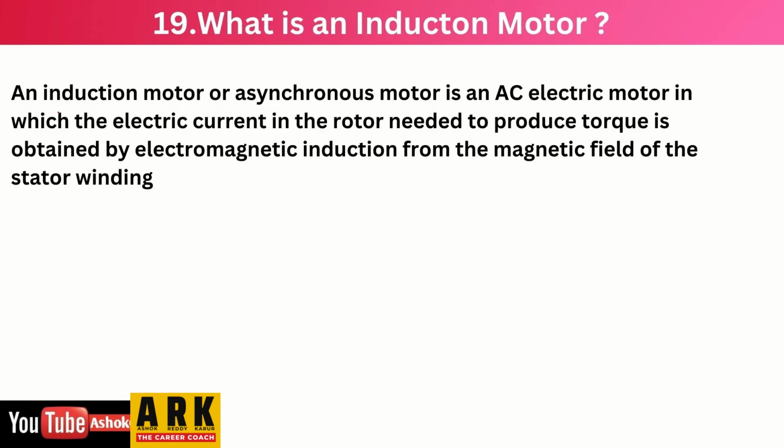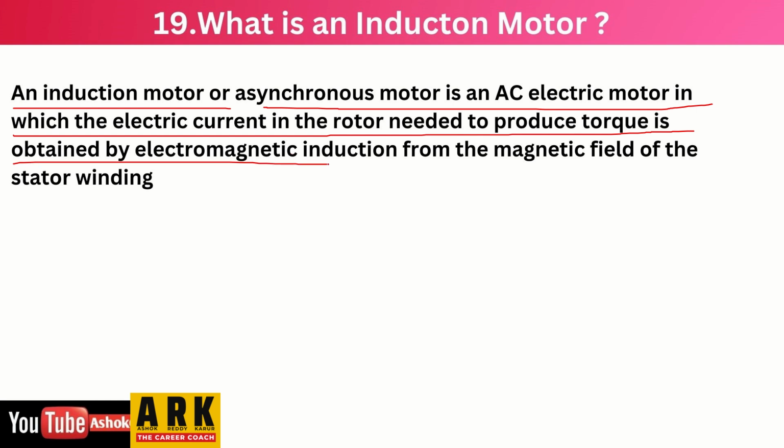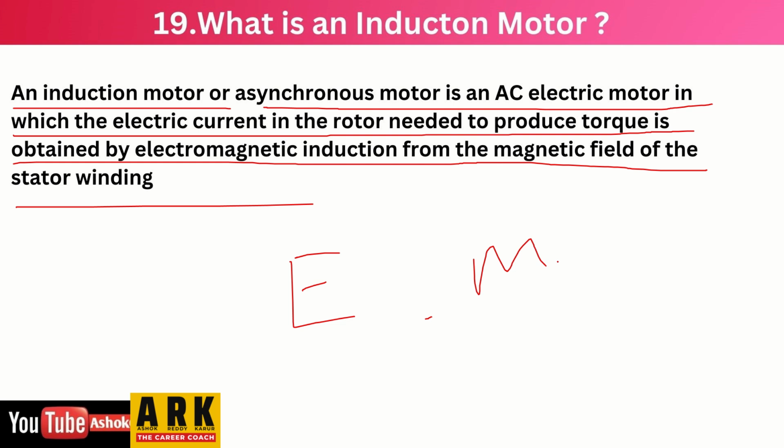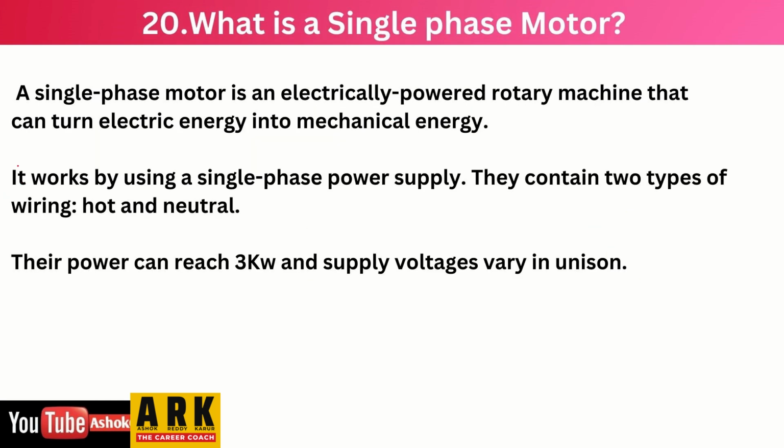So what is an induction motor? An induction motor or asynchronous motor is an electric motor in which the electrical current in the rotor needed to produce the torque is obtained by electromagnetic induction from the magnetic field of the stator winding. Electromagnetic field, EMF, okay.